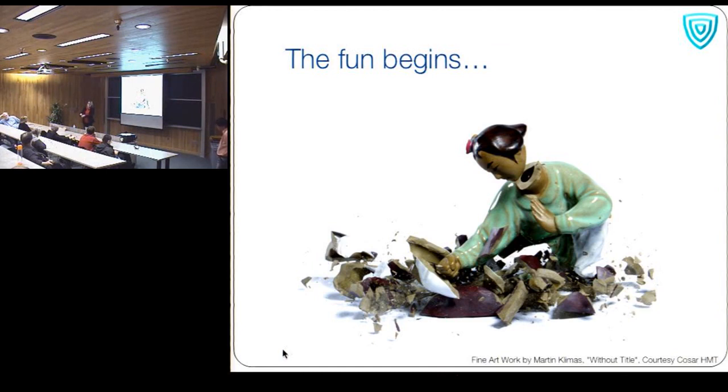volume element. So in the micromechanics model, what we're doing is taking an input stress and strain and trying to predict an increment of stress. But we're not using anything like a periodic boundary condition or the kind of thing that you would need if you were truly using an RVE kind of approach.